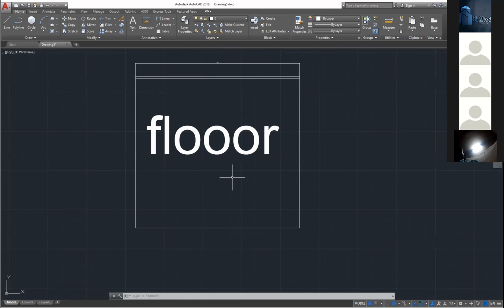You can bear with me that for those of you who are familiar with this software, when you leave from 2 dimensions and maybe you want to start doing 3 dimensions in AutoCAD, you have to get rid of the doors and the windows because at that point they are not important, okay? Now, a lot of people will go in there and start deleting, but if you set up your layers very well, with different layers for doors and different layers for windows, at that point you just freeze them, okay? It's not like you're deleting them, but you just freeze them and they disappear from the design, giving you a clean space to work only with your walls, okay?